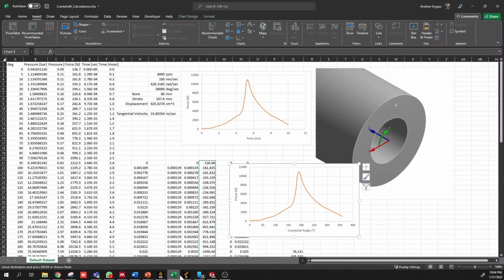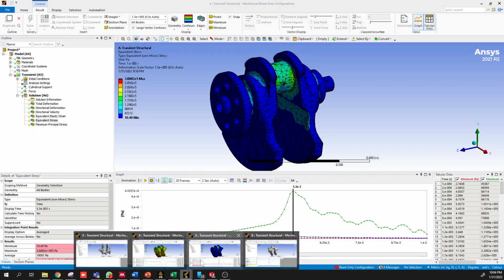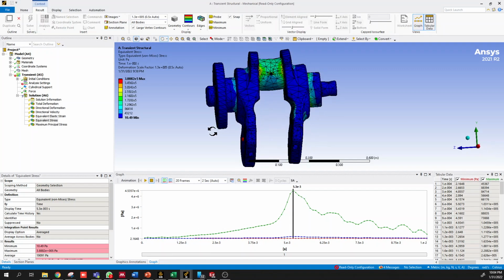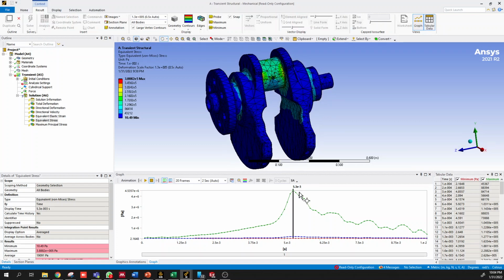You can see, if we go to another analysis model, how the peak for the bending only model, where we're not including the rotation, the peak stresses that are occurring here are approximately, we'll probe here, about 0.2 MPa, so not a huge amount for steel for this load level, but these are the stresses that we're seeing.